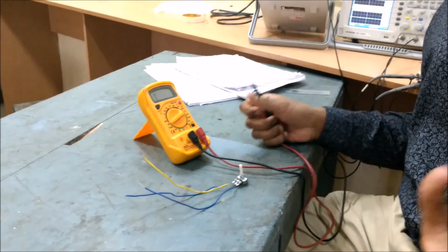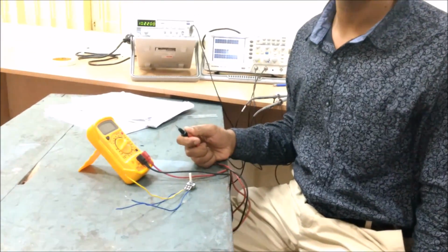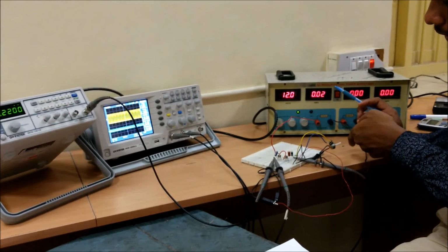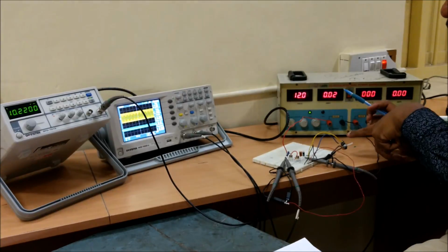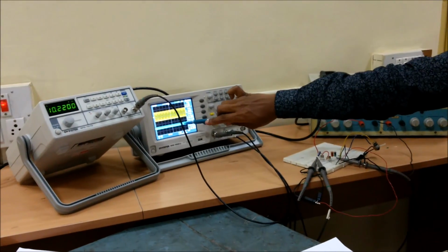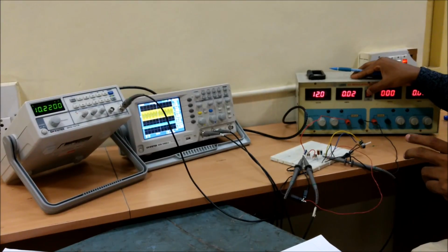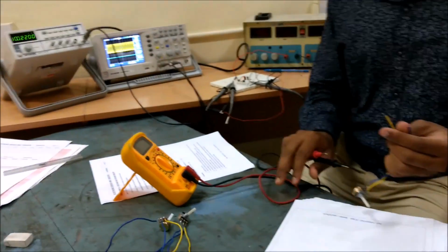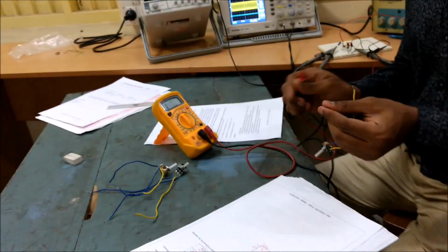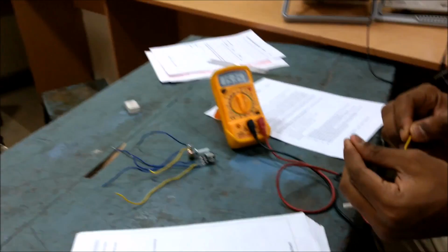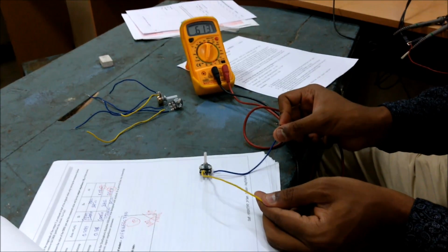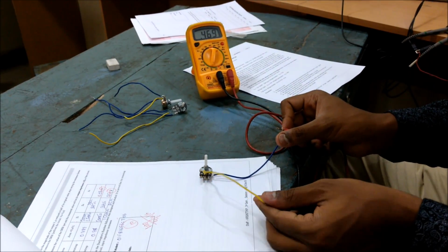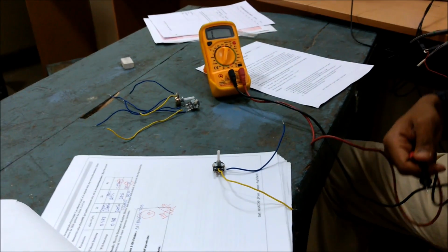This is about the circuit without bootstrapping. Let me connect the bootstrap, then we will see. Without bootstrapping, you can calculate the output impedance. I connected the 1 kilo ohm pot, and the output is exactly reduced to half. So now we will see the output of the pot, the pot impedance. Guys, we can see that the output resistance is almost 469, that means 470. It's the output impedance without bootstrapping.